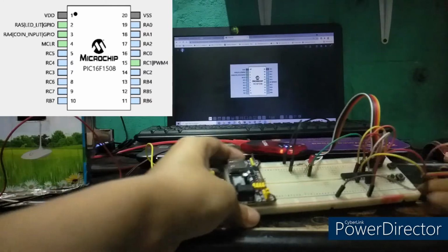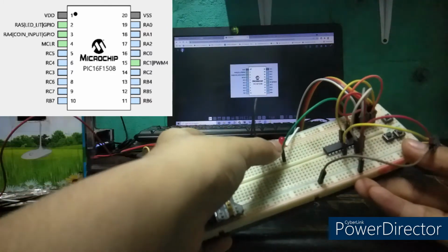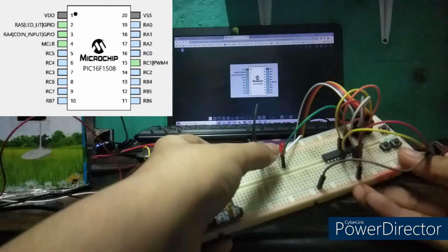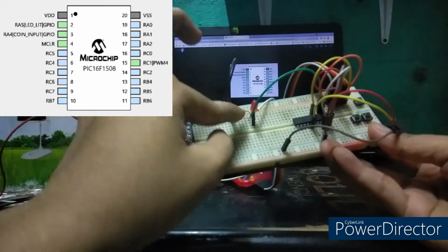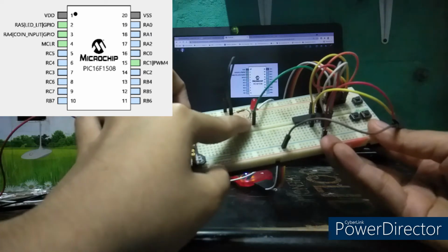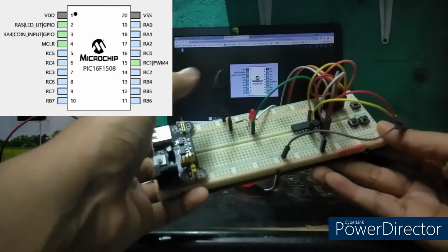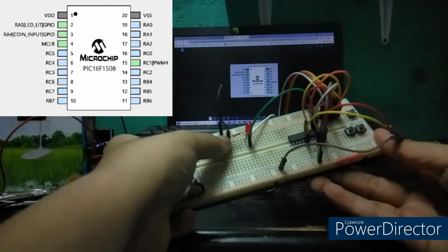And then after that, we connected an LED to our IC, connected to the second pin of our IC. This green wire here is connected to the green wire there. And then we connected a 360 ohm resistor in series with our LED. Be mindful of the polarity of the LED, so it will light up as our indicator for the candy machine, and then ground the series connection.